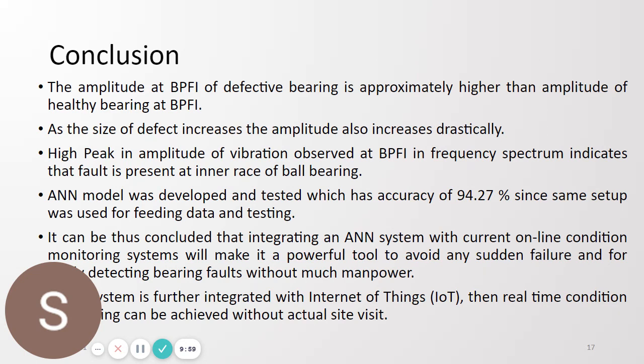So, conclusion: the amplitude at BPFI of a defective bearing is higher than the amplitude of a healthy bearing at BPFI. As the severity increases, vibration amplitude increases.